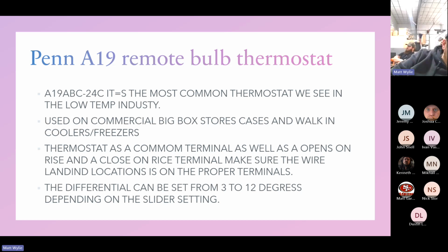So on those thermostats, the common terminal has an open on rise and a close on rise. Always make sure it's landed on the proper terminals. You hook them up and think everything's good, and then it doesn't cool until it gets hot, or until the temperature drops. Closes on rise.